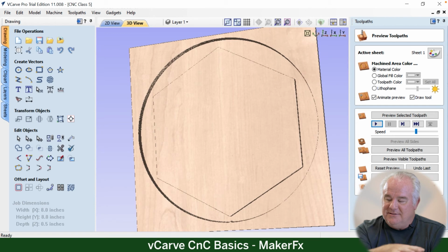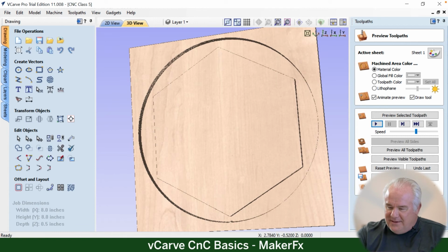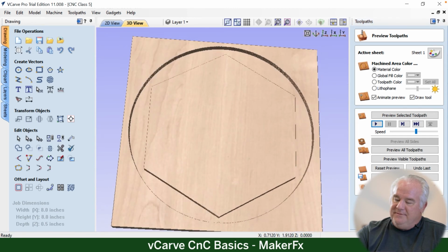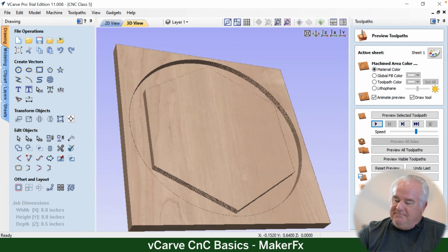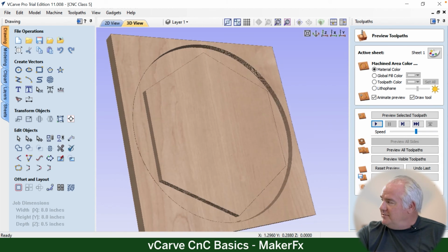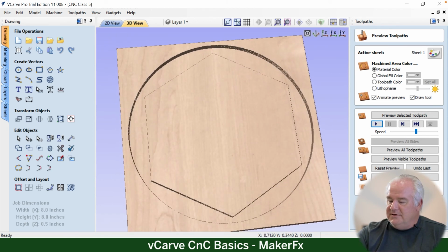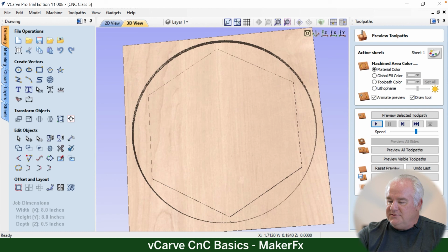So when we take the design file out to the machine, one of the things we're going to do there is recalculate, just one last time before we actually create the G-code file. Sometimes with pocketing operations, the spacing that you have and the size of the bit doesn't get you the outcome that you're looking for. So that's one benefit of doing the visualizer. I think when you get into VBit as well, Ron, you'll be able to better see how some of the VBit work is doing.